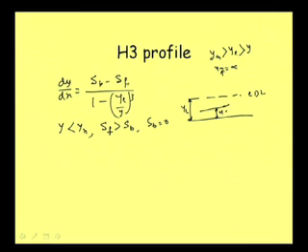So, SB minus SF becomes negative. When SF is greater than or equal to SB, it has a positive value, and minus any positive value becomes negative, and SB is 0. For the denominator, y is less than yc. So, when y is less than yc, the ratio yc by y is greater than or equal to 1, and that cube is also greater than or equal to 1.